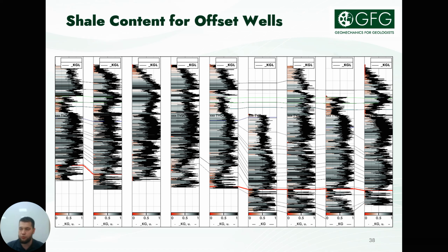Another type of input data is gamma logging, which is used to recalculate clay content. Clay content in turn can be used in the future to calculate the friction angle. The internal friction angle has a serious impact on the borehole stability, which we have already discussed in detail in lecture number 06.